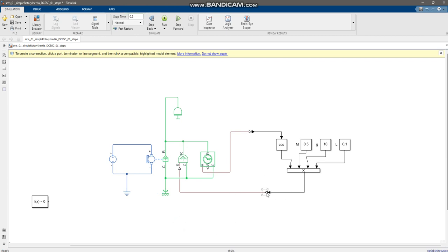And there's some other thing that I quite forgot to do, and that's the insertion of a negative sign prior to connecting the two torques together. If you remember the mechatronics model that we were studying, we defined the problem in a manner that the DC motor will be wired to impart a counterclockwise torque, and based on the starting position of our rod, the gravity was imparting a clockwise torque.